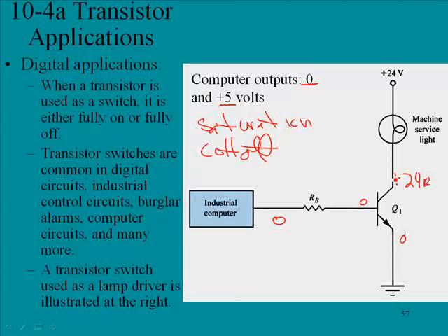I don't want to confuse, I think that is negative. But the transistor in this case essentially looks like an open switch because there is no voltage drop. Well, there's a voltage drop across it, but it's just the supply voltage here, and this is not conducting, and there is no voltage across the light, so it is off.